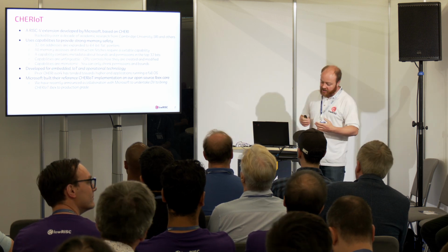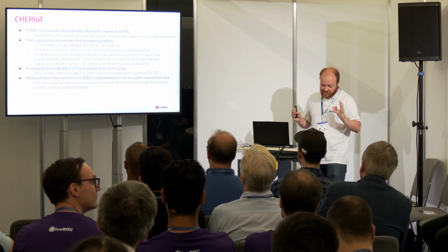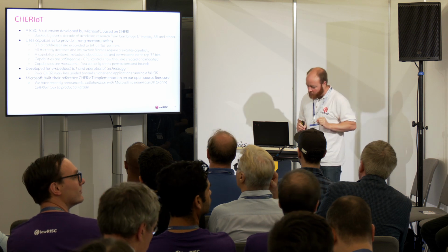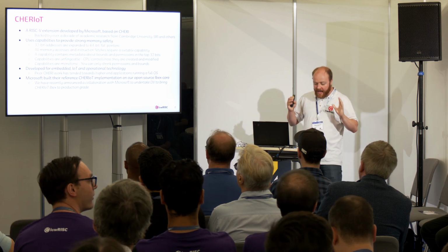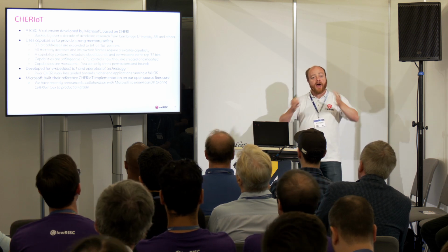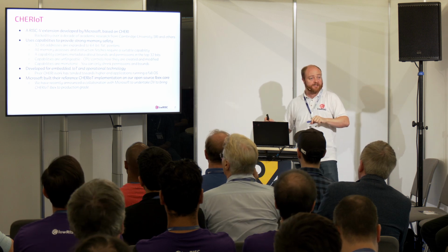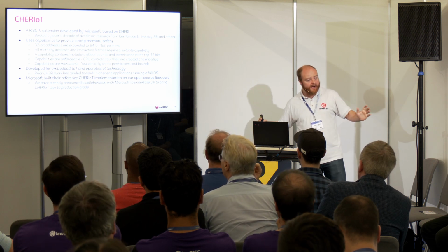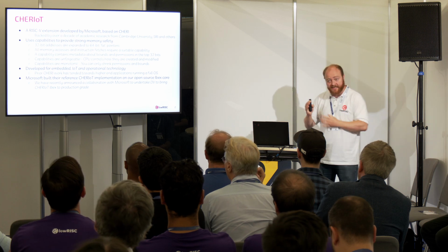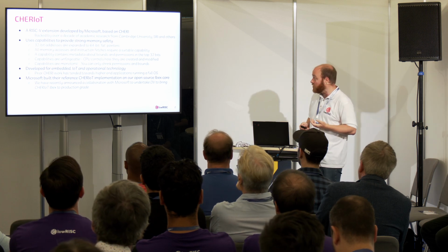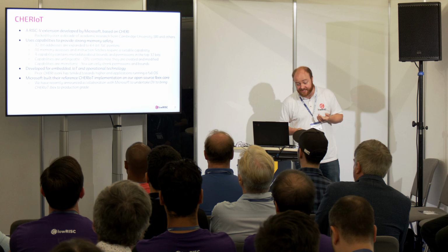The CPU starts with effectively 1 capability, well, in the case of CHERIoT it's actually 3, but let's just say 1 to keep it simple. 1 capability that allows you to do everything, and then you partition that down and shrink it down and hand it out to different parts of the system. And then they can't expand back out again. And this allows you to isolate different parts of your software to provide these strong security guarantees.